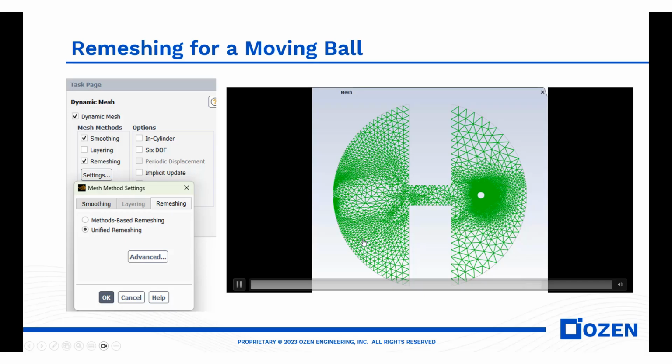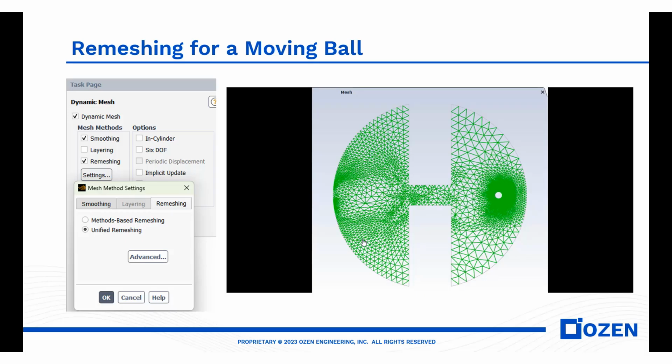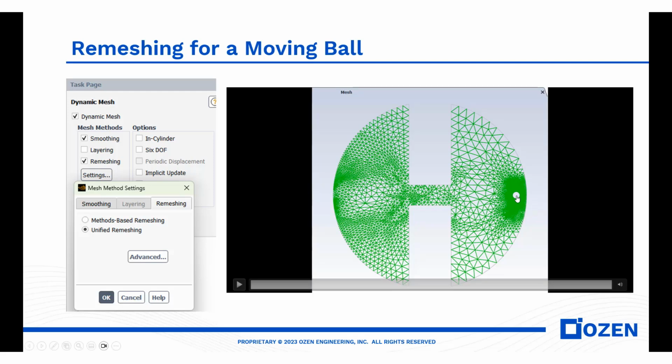So we need deforming boundary conditions there. And for the horizontal motion definition, again we have to use a profile or a UDF. These examples are taken from the Ansys training materials.